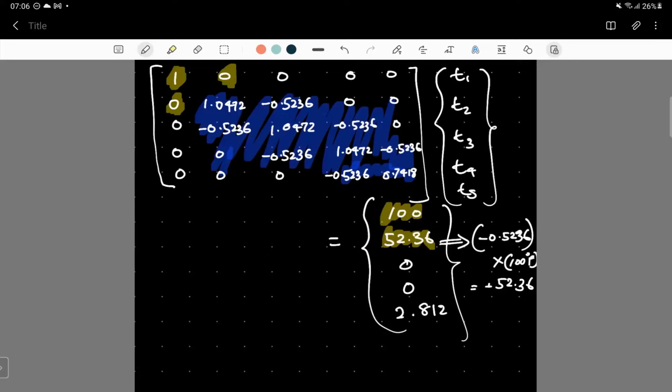The second up to the fifth equation correspond to rows of unknown nodal temperatures, which can now be solved using the Gaussian elimination procedure.